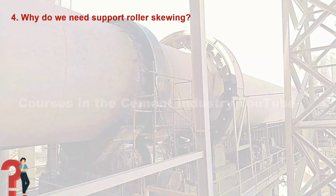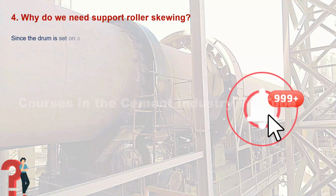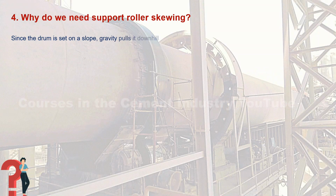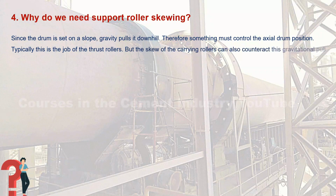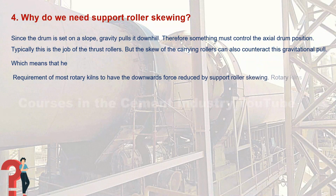Question 4. Why do we need support roller skewing? Answer. Since the drum is set on a slope, gravity pulls it downhill. Therefore something must control the axial drum position. Typically this is the job of the thrust rollers. But the skew of the carrying rollers can also counteract this gravitational pull, which means that most rotary kilns require the downward force to be reduced by support roller skewing.